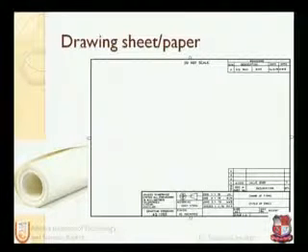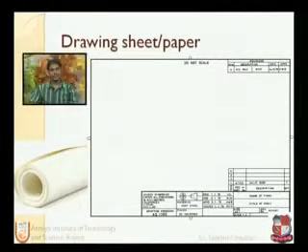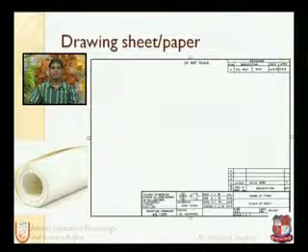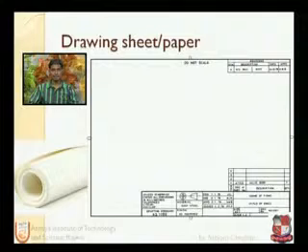Normally, the recommended dimension of the title block is 185 by 65. The title block contains certain information, such as whether the drawing is in first angle or third angle projection, the drawing title, the component name, the drawn or checked initials, and the scale. The scale we are going to discuss later. It also contains the bill of material and the part name; the part name and bill of material table can be created on the title block.